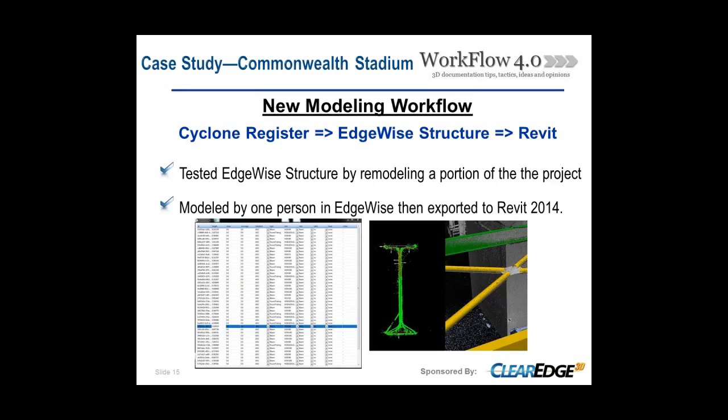And basically what you're looking at below there is just one of the QA/QC tools. The 2 screen captures below show what happens once you click on a beam and start going through the QA and QC. It not only shows you how that beam fits, but you can go through and change some of the parameters. So if that beam size was a little bit bigger than what it really appears to be in the cross section, you can change that right there in the QA and QC tools, which definitely saves a lot of time.